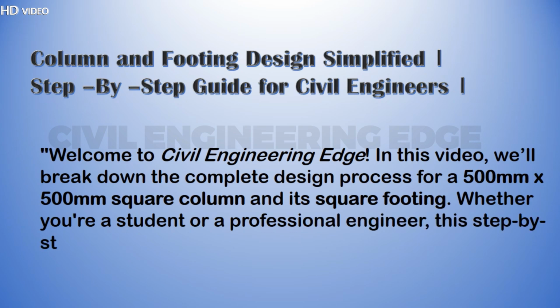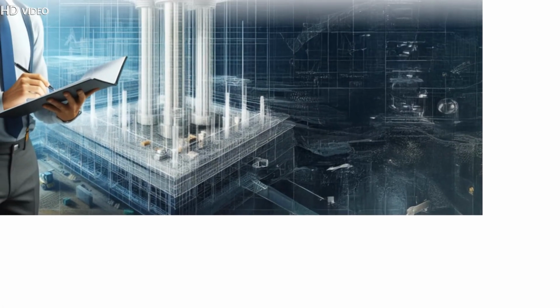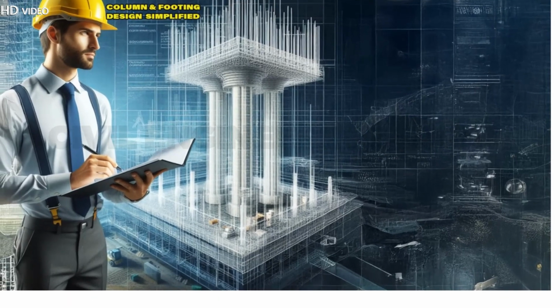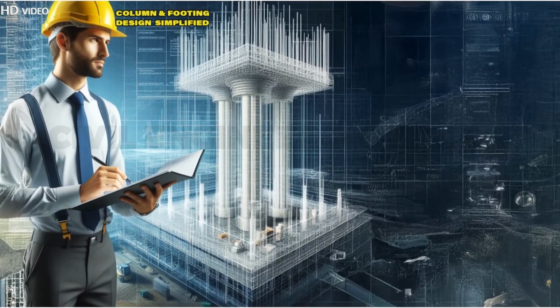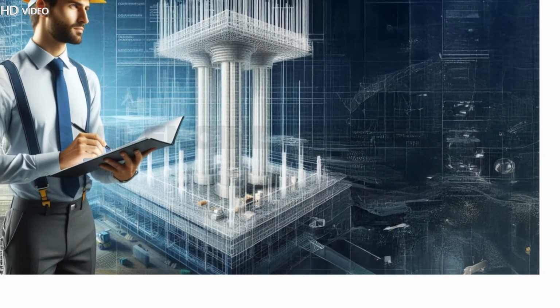Section 1. Given data and problem statement. We have a 500 millimeter into 500 millimeter square column carrying an axial load of 1,500 kilonewton. The safe bearing capacity of the soil is 225 kilonewton per square meter, and we are using M20 grade concrete and Fe 415 grade steel. Let's begin by designing the column reinforcement.